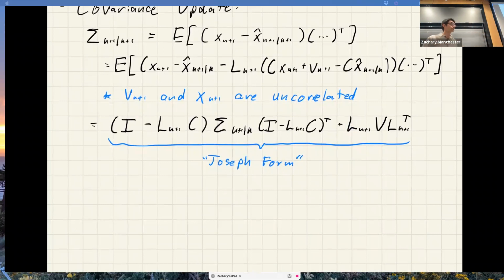Okay. Is this actually numerically stable or is it just less numerically unstable? The Riccati equation is numerically unstable. We'll get into this. Yeah, I guess. So the naive Kalman filter equations as written are not great in terms of numerical stability. There are many, many hacks to fix them up. But in this case, it's sort of benign and it's sort of fine. But yeah, this one is better than the not symmetric options. There are even better options with regard to numerical stability if you care. So if you're going to write like a sort of industrial strength Kalman filter to use on a robot and it has to work, you know, if it's on a car and it needs to work every time, guaranteed, and it can't blow up and whatever, there's some other tricks to play.